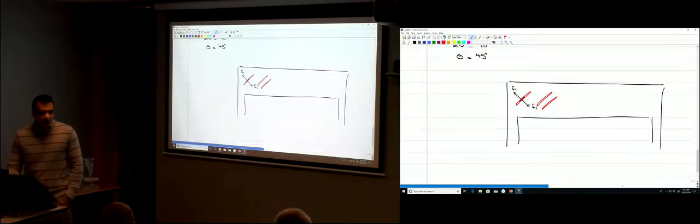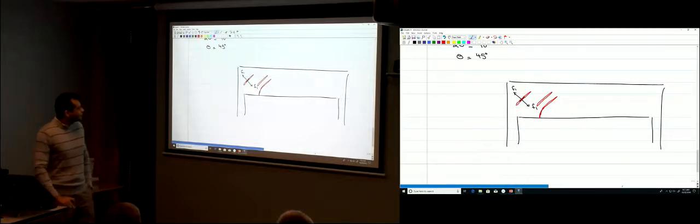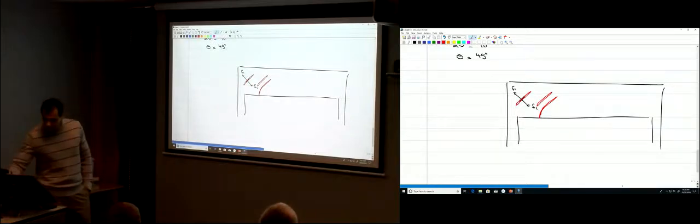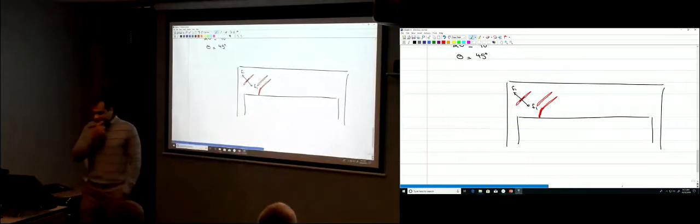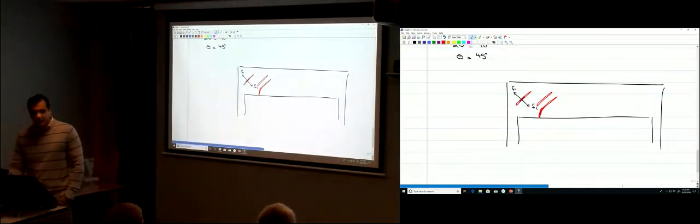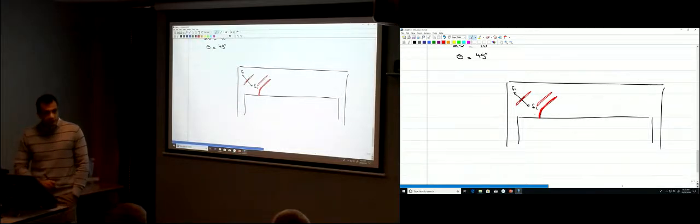the normal stresses at the bottom of the beam will start to develop, right? Because of having bending moment. So you're going to have some bending moment over here. So it will develop a flexural crack, and this flexural crack will join this web shear crack, and it will develop just one big crack here. This crack will not continue here because here the concrete is in compression, right? So you're going to develop this flexural shear crack. It starts due to the flexure at the bottom of the beam and then due to the shear force.